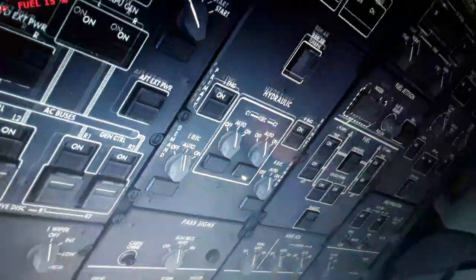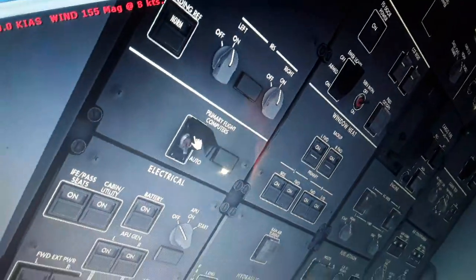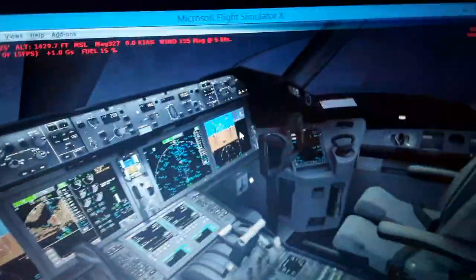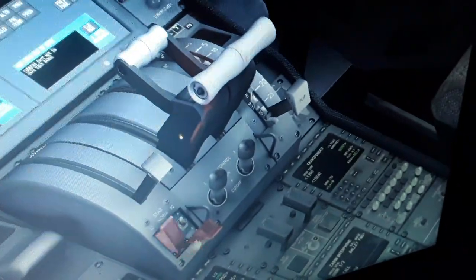So you have a failure that affects the flight control computers. You will lose the auto trim function because you have an automatic trim. This is a fly-by-wire aircraft. You can trim itself by the flight control computer. So you will lose the auto trim if you have a failure that affects either the left and right horizontal trim stabilizer over here. So this is for all Boeing 737, 747, 757, 767, and Boeing 777, and also Boeing